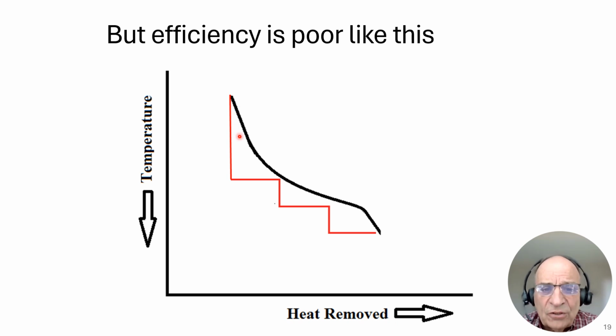And why it's shown curved here is because this is natural gas at this point, and at this point it's LNG. But natural gas has multiple components, some of which start to condense out at about minus 60, minus 80 degrees Fahrenheit. Like, for instance, propane. If there's any propane or heavier hydrocarbons, they'll start to drop out here at perhaps around minus 60 degrees Fahrenheit.